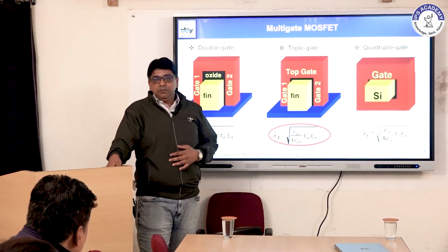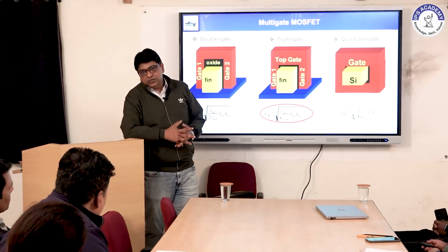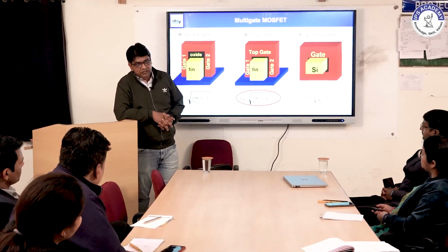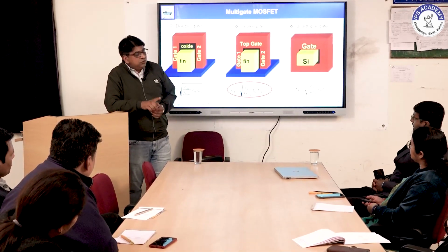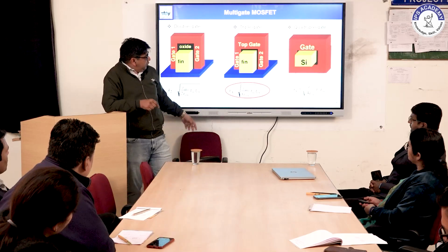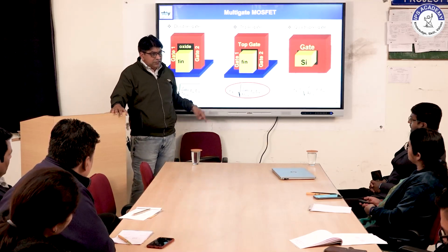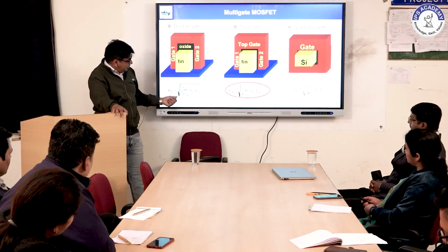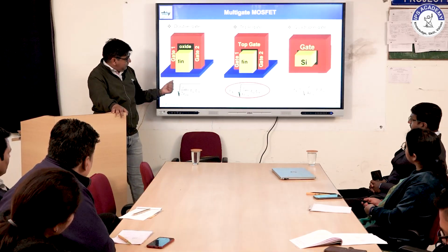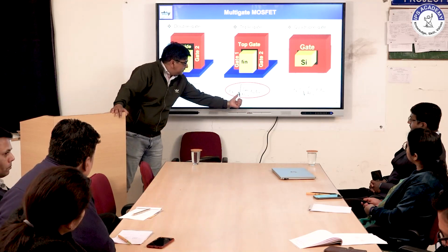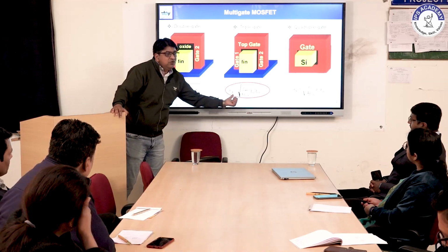Triple gate also improves your electrostatics, which means it also increases the control over the channel. This again continues with the triple-gate FinFET, or tri-gate as we can call it. You observe this with the help of the electrostatic integrity factor lambda 3. Here everything is the same, only the 3 is there, so the value is going to reduce.